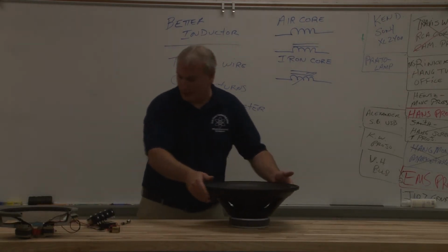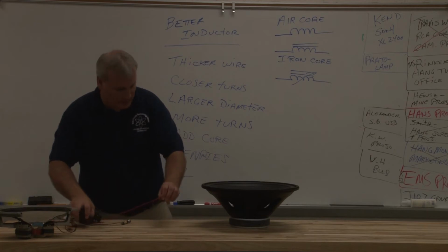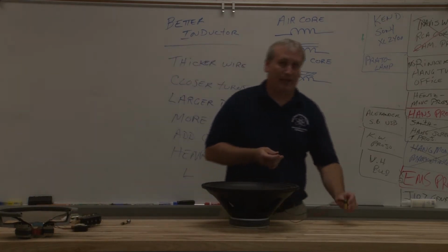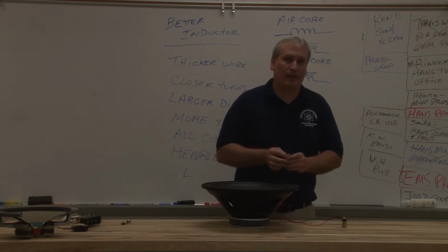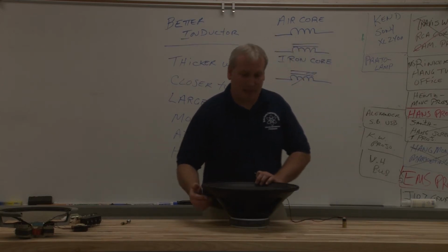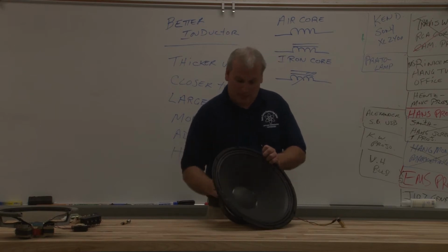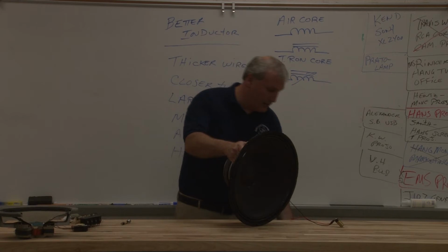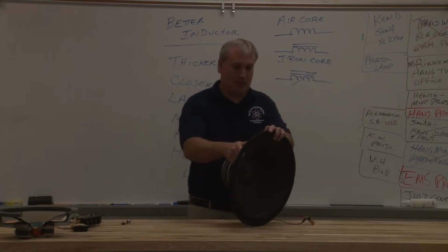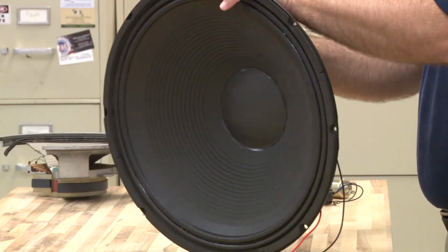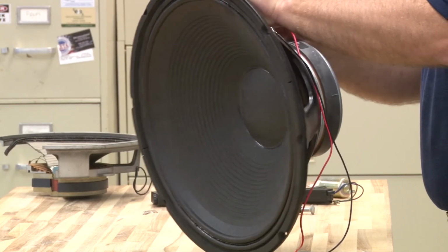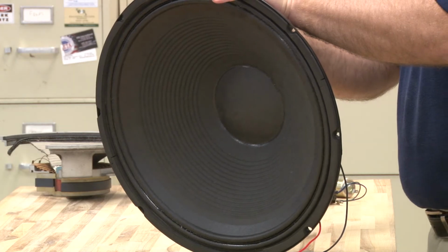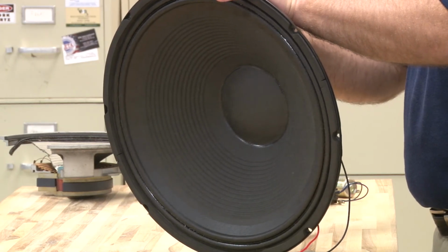Here's one that's not all cut up and still functions. Here's my 9-volt battery. Now we said at one polarity, the speaker's going to push, right? And in the opposite polarity, the speaker is going to pull. So what I'm going to do is I'm going to take this speaker, I'm going to hook up one side of my 9-volt battery, and I'm going to hook up the other side of my 9-volt battery to the voice coil. Now, right now, the speaker's doing what? And if I do it really quick, you can hear it pulsing away.